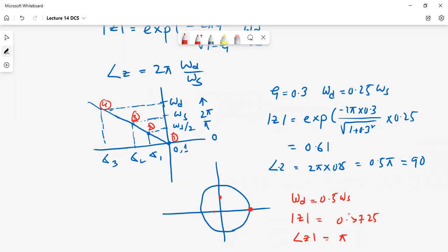So you're getting a magnitude something like this. Okay, so gradually you'll find a spiral kind of shape, a logarithmic spiral. So you'll find a constant zeta line, something like this. Is it okay? It will be based on the calculation, so you don't have to worry too much about how the thing is coming, rather just follow the steps.